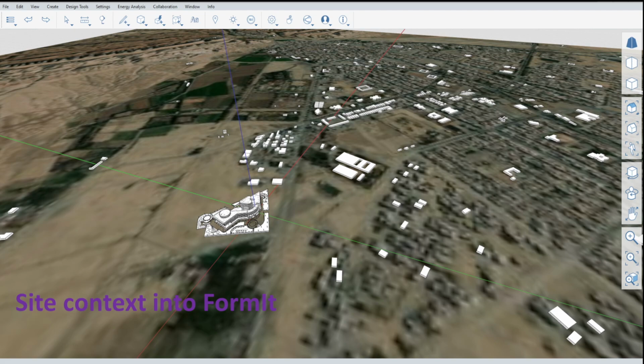Site context into format. First of all, we have to market the conceptual design decisions. Building size, area, occupant load, height, number of floors, location on site, construction type, and arrangement of rooms for proper egress, doors, exit discharge, door swing direction, and lighting, HVAC, and indoor air quality, insulation and fire rating requirements based